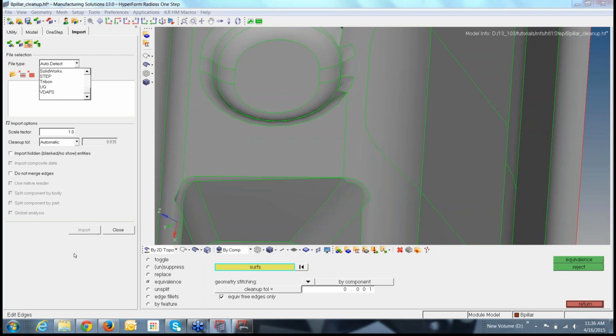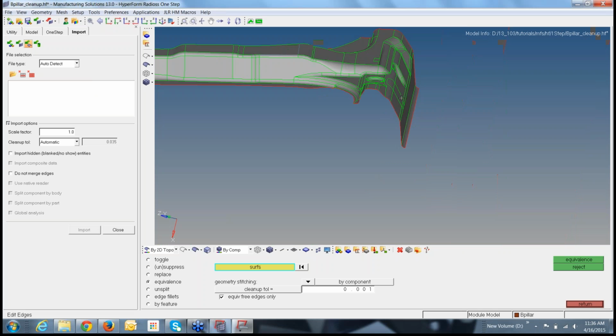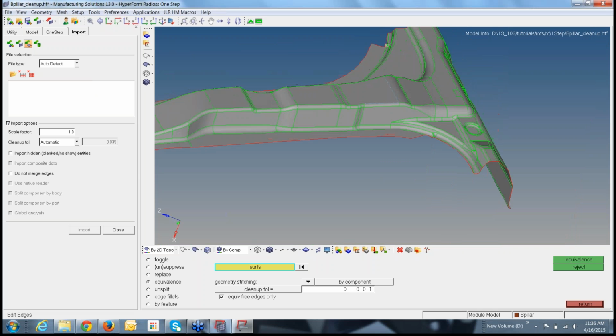So you can export your CAD geometry, your skin for your component, which is to be extracted for a mid surface, in any of the formats. Can be IGES format, STEP, any of it. So I hope you are clear about the process of cleaning up your geometry.